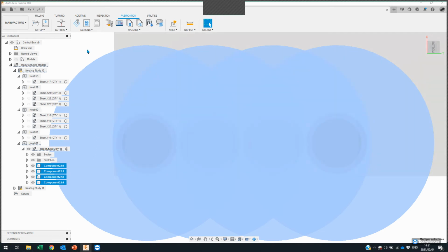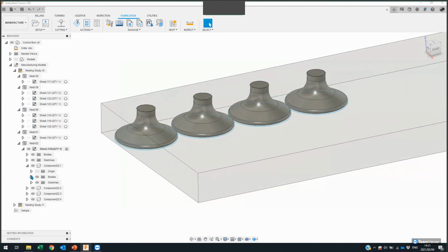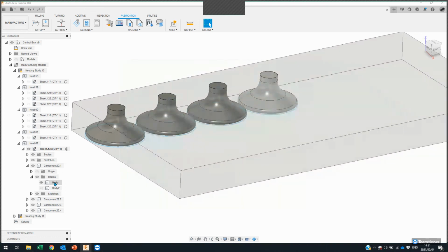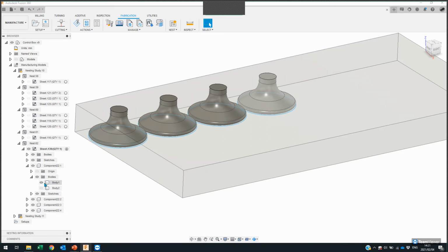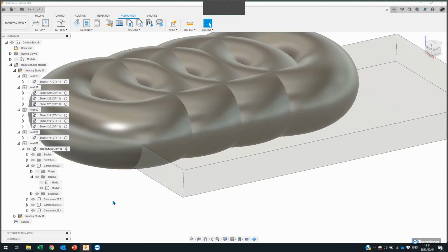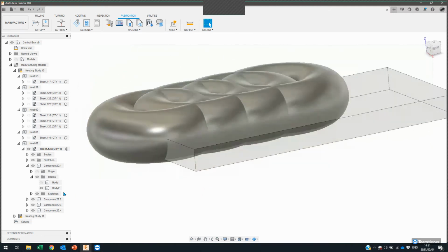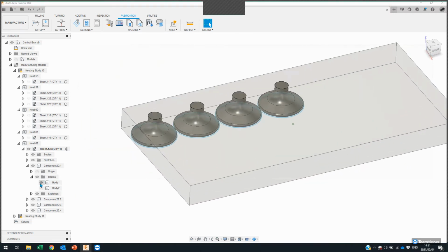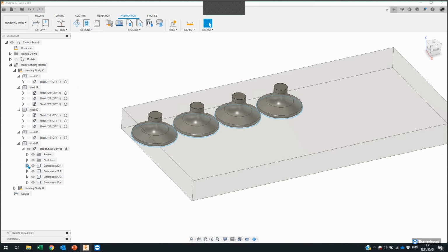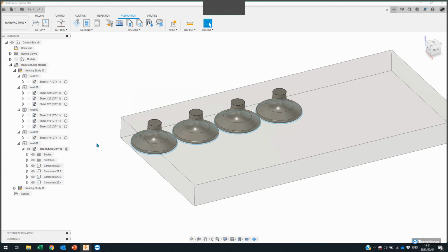Now you might see these big round discs highlighting as well, just to show you what happens with the multiple bodies. I actually designed this component with 2 bodies, and we'll see body 1 is the visible body that is brought into the nest. If I switch the visibility of that body off and then switch body 2 on, I had created these big donuts basically, just as a test to see if it would bring that in, and it only brings in that first body. So just reiterating on what happens there with your standard components when they are brought into a nest.